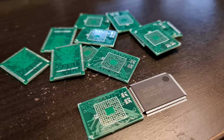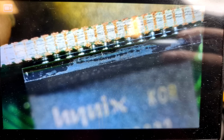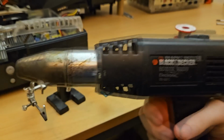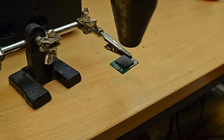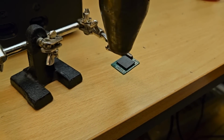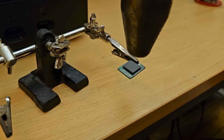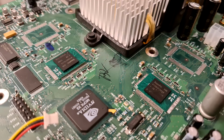If you read online, you'll find that a lot of people are quite afraid of BGA, and I suppose I was too. This is my first time really doing BGA soldering, and I did not have good equipment at all. I used a heat gun. These things are meant for stripping paint off the wall. It's not for doing precise soldering, but I made it work. It was good enough for the time. Though saying that, I had missing connections rather than short circuits, primarily. It went extremely well for the first 4 chips.